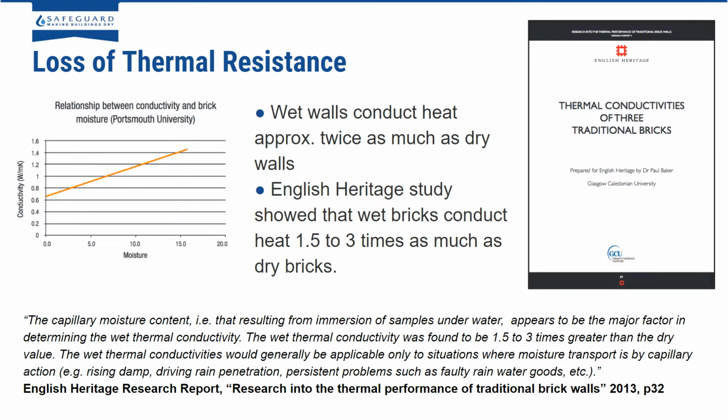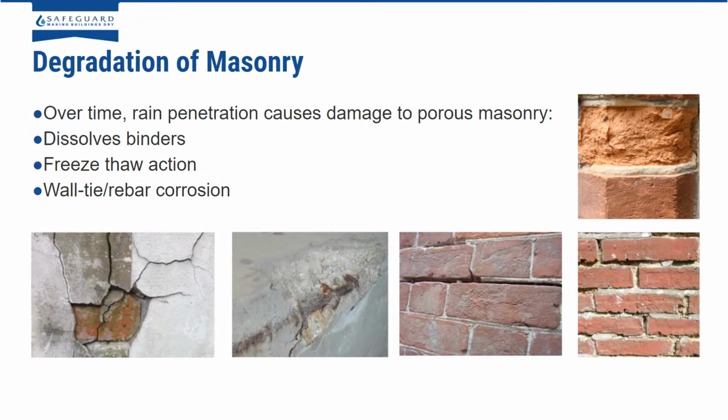You'll actually burn your hands. It's the same sort of idea. It's shown here that a wet brick will conduct away twice as much heat as a dry brick, and so by doing that it's going to increase the amount of heat loss in your property, and so will especially during these winter months, increase your energy bills.